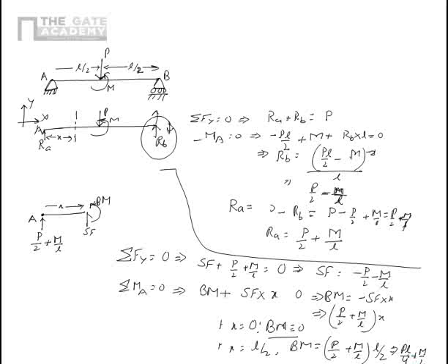But because there is a moment also and it is at a center, so half is shared there, so it is adding up. Now, for this portion of the beam, this is the way it behaves. So the shear force is a constant, which is nothing but the sum of the half of the applied force and the moment reaction, and the bending moment is again the same thing.